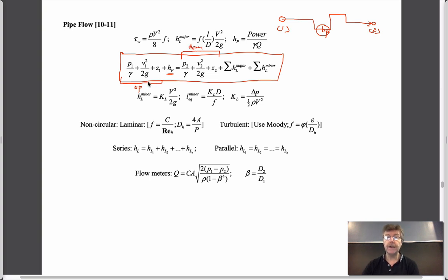And what we've talked about for the last couple of sessions, first in the tail end of dimensional analysis, and last time in our discussions about friction factors, is that we'd like to be able to account for these frictional losses. These are the dragging my bag across the table losses that are not reversible. They're expended one way. As you flow water one way, if you flow it back, you don't regain them. You've lost it to heat and sound. And they fall into the categories of minor losses, which we haven't said anything about, but are really due to the fact that we have bends in the system.